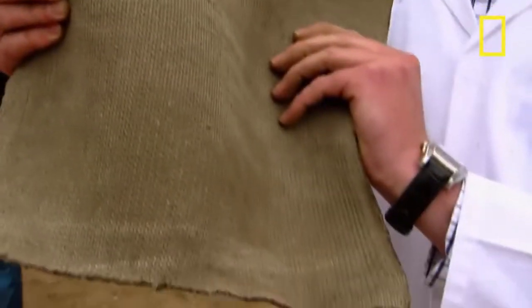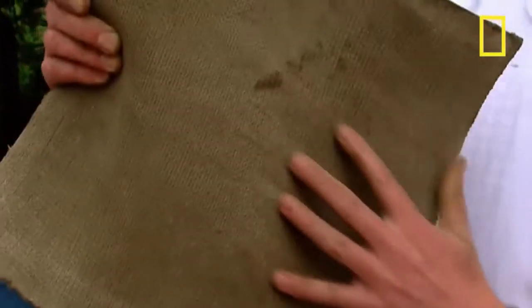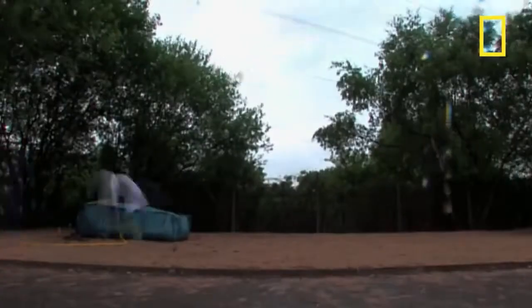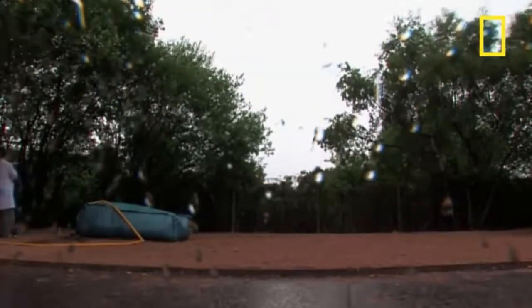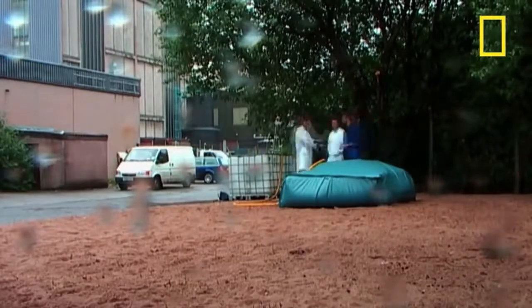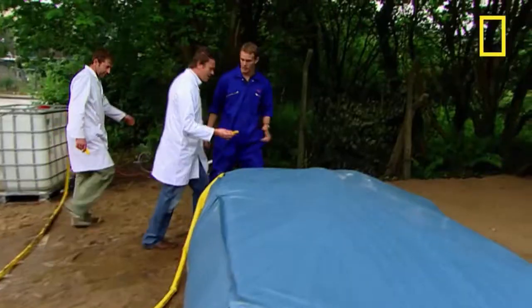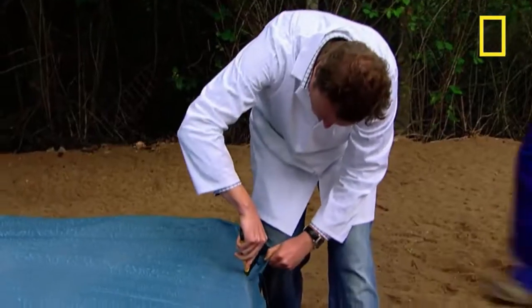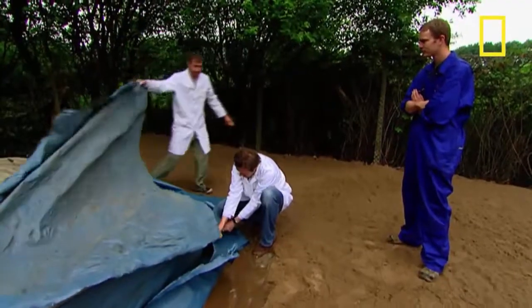The concrete cloth is made up of fibres which evenly absorb water until all of the cloth is saturated. The inspiration came from the plaster casts wrapped around broken bones in hospitals. Once the cloth is completely soaked, the process of hydration begins and the plastic casing can be removed. At this point, there's a window of around 5 hours for the canvas to be raised into its final position before the concrete starts to set.